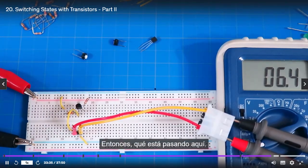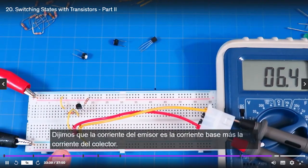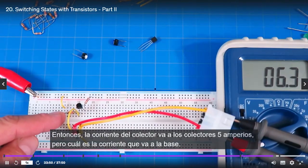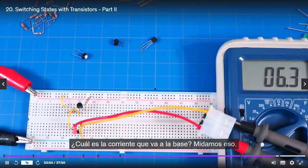So what is going on here? So wait a minute, remember what we said. We said that the emitter current is the base current plus the collector current. So the collector current going into the collector is 5 milliamps. But what is the current going into the base, right? It has to go someplace. What's the current going into the base? Let's measure that, all right?